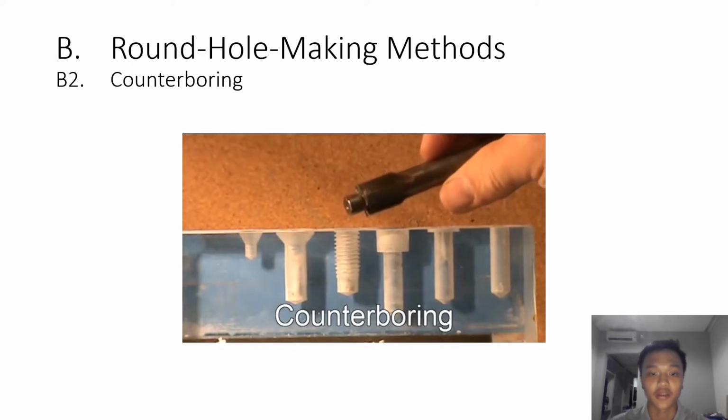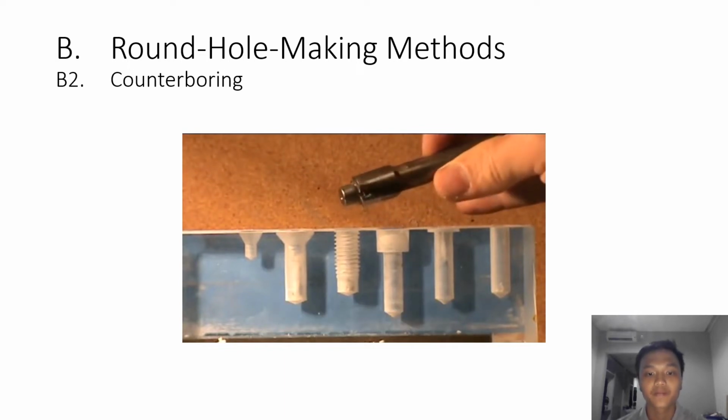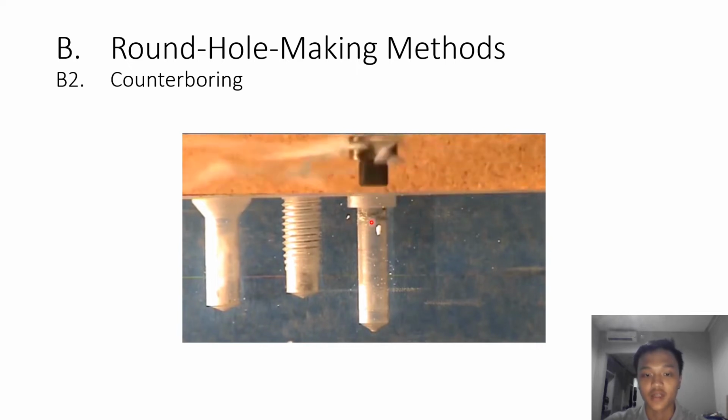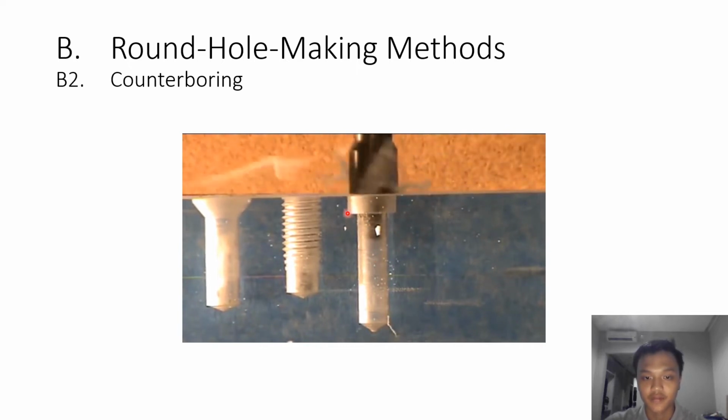This is the process of the counterboring operation, making a hole that's designed to be used with a socket-head cap screw. Notice the end of our counterboring tool has a pilot on it. The counterboring operation makes a flat bottom result. Just like this, flat bottom.